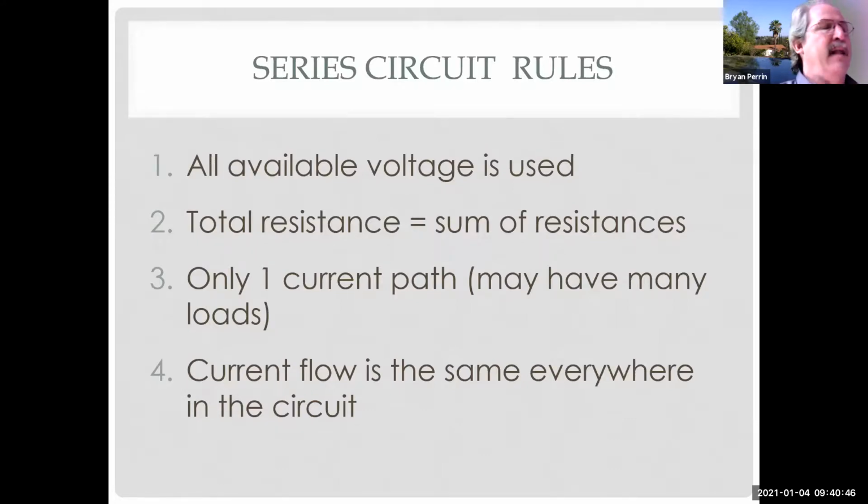So that is really one of the tricks we use, this rule that current is the same everywhere. For example, if I want to test a fuel injector, I could dig right inside the engine, find that fuel injector, and put a tester on it to measure my current. Or I could measure it at the computer that's turning it on, which might be much easier to get to, because the current's going to be the same in both places. So should I test it at an easy spot or a hard spot?